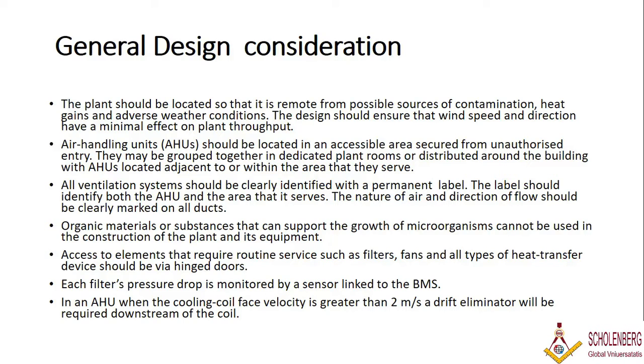Each filter's pressure drop should be monitored by a sensor, and it should be linked to the BMS system. So these are some of the general AC considerations.